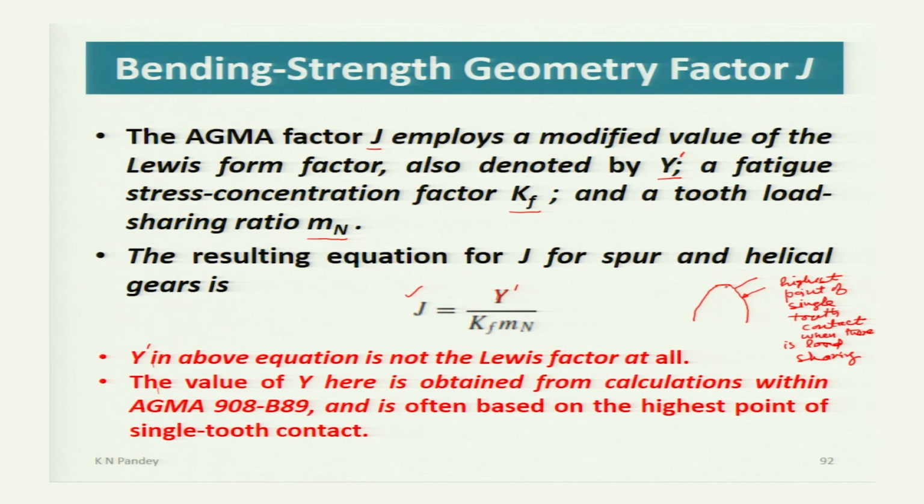When there is no load sharing, this is the point where maximum load occurs, but under load sharing condition it occurs slightly below, and so the bending stress will be lesser.